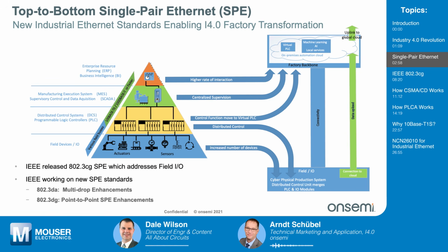In this pyramid, everything that you see down to the yellow pyramid, so basically to the distributed control systems and the PLCs today, is dominated by Ethernet. This is what we today call the classical industrial Ethernet. This is systems working on 100BASE-TX. So that's basically the same that you plug into your computer today, 100 megabits, and there's a strong move towards faster speed with 1000BASE-T, which is gigabit Ethernet, or even faster. As you create more data, you have more demand for faster data up in these levels.